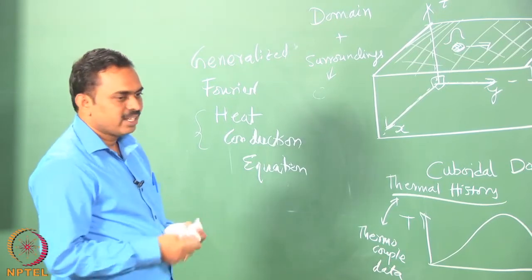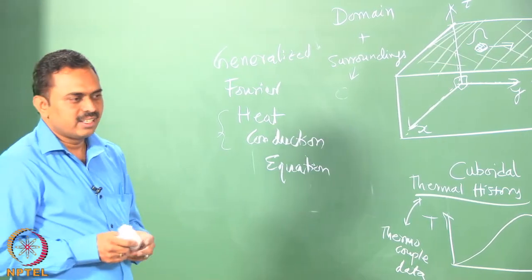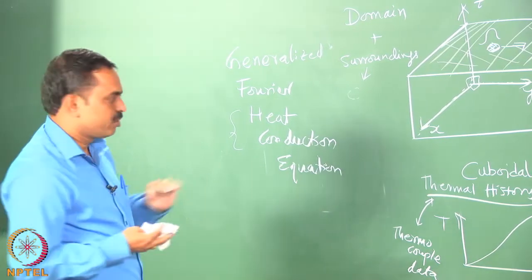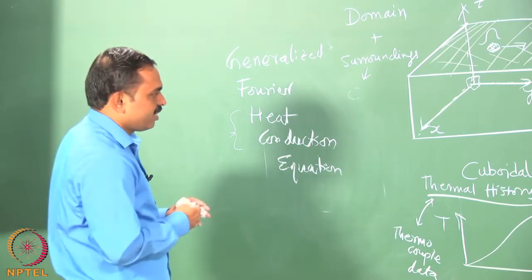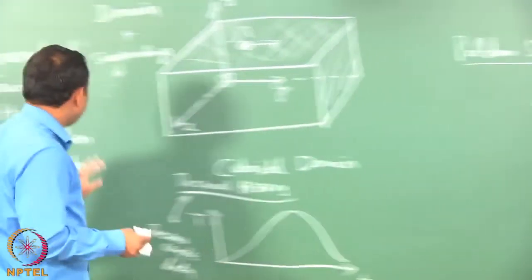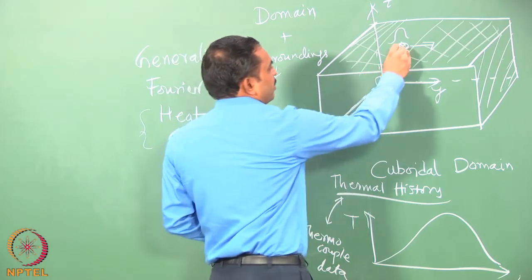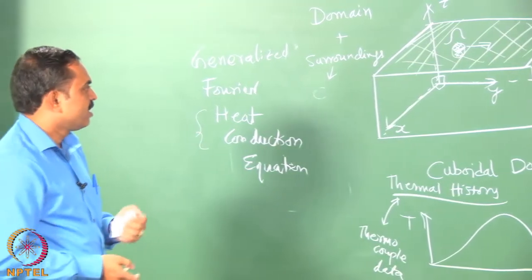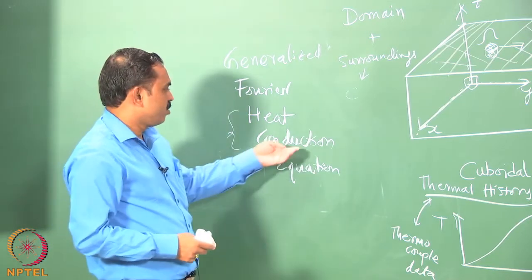Okay. And then one may also think the heat is actually released by radiative loss on the surface, and unless we take into account how much radiative loss is happening, we are not able to proceed with the solution of the equations, and therefore, maybe it is a radiation equation we are going to solve. Again, that is wrong, because the radiation is going to be covered under the boundary condition, and we are actually solving only the conduction equation within the domain. And the domain will have, for example, where the liquid is going to form, the liquid may have some advection, there may be fluid flow taking place, and shouldn't we say that fluid flow also needs to be taken care of? We are considering convection also to be part of conduction.